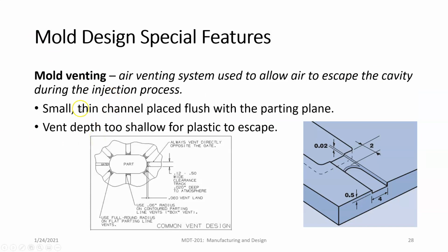Still looking at some special features. We have mold venting, where we need to allow the release of air. If we look at this design right here, I think it's a little bit easier to see. So the gate, remember, the gate is where the plastic comes in.